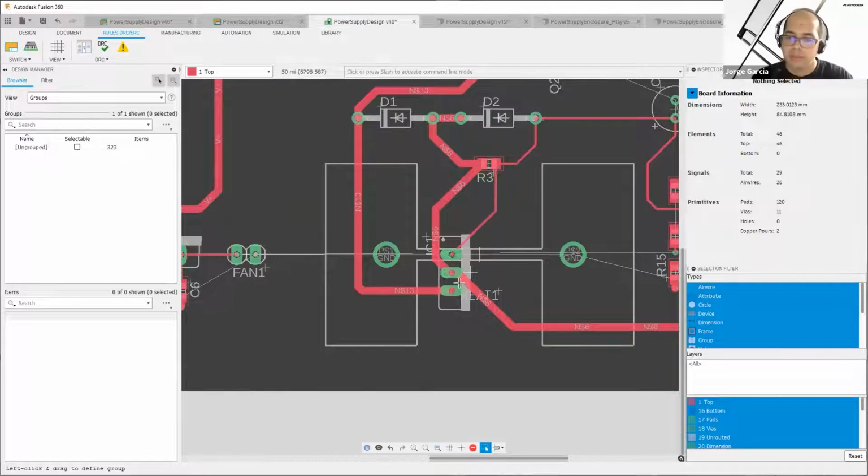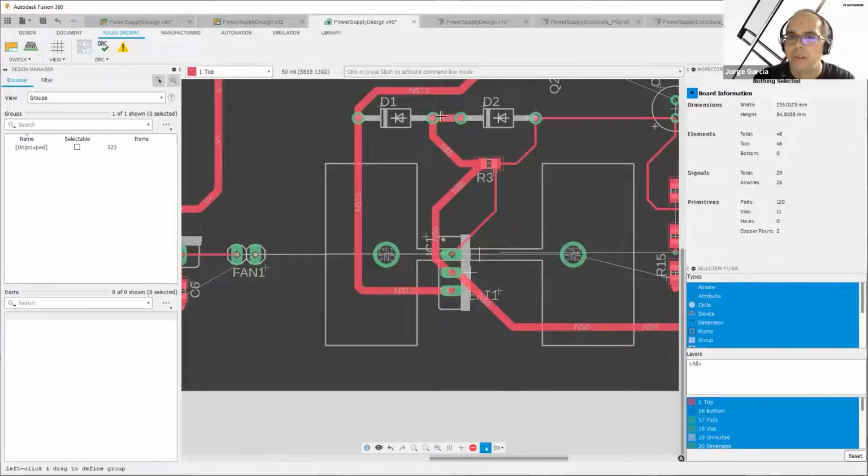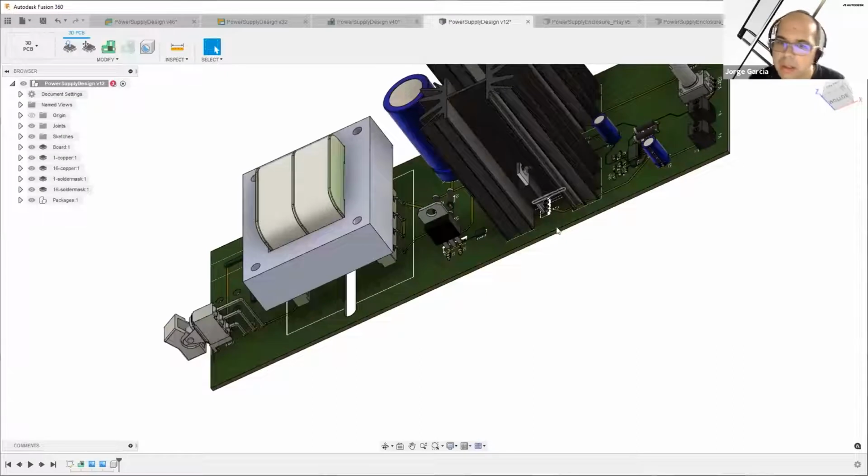And this is something that's unique to Fusion 360. So I could actually right here just finish the move, finish making the rotation, and then have it reroute again. But I think the concept is demonstrated. You have something here, you can just fix it, and then it will automatically try to reroute everything on the 2D PCB, so to keep everything in sync and in a reasonable state.